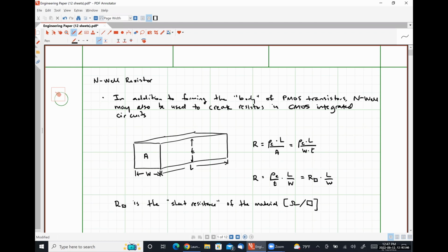So there are a couple of things to talk about here regarding the concept of sheet resistance. This unit of ohms per square is an odd unit if you're not used to it, because what it literally means is a square amount of area has a specified resistance. It does not matter whatsoever what the dimensions of that square is, okay?